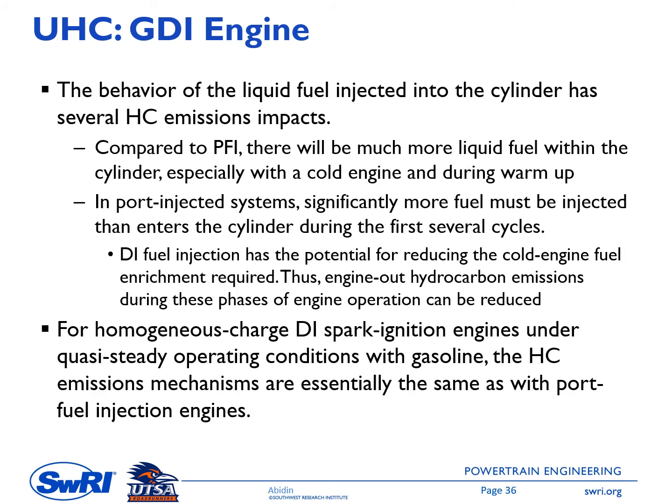How about the unburned hydrocarbon in the GDI engines? The behavior of the liquid fuel injected into the cylinder has several HC emission impacts. Compared to PFI, port fuel injection, there will be much more liquid fuel within the cylinder, especially with a cold engine and during warm-up operating condition. In a PFI system, significantly more fuel must be injected than enters the cylinder during the first several cycles. This is because some of the fuel will remain in the intake port, so we need to compensate for it by having more injected fuel. For the DI, we don't need to do that because DI can have the fuel amount as needed by the engine.